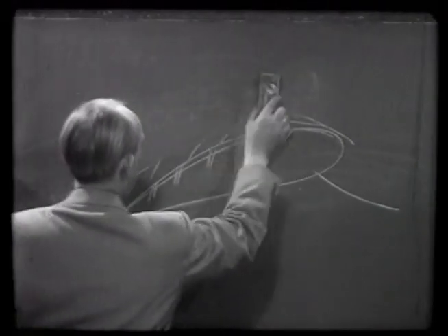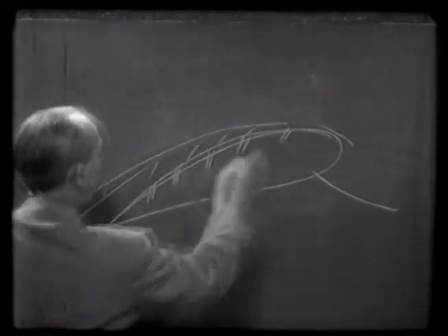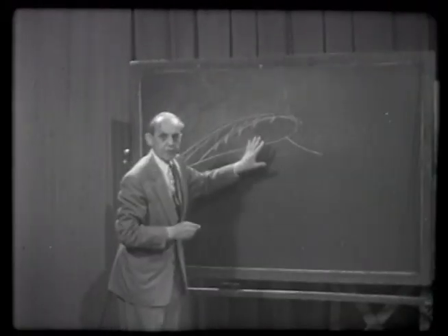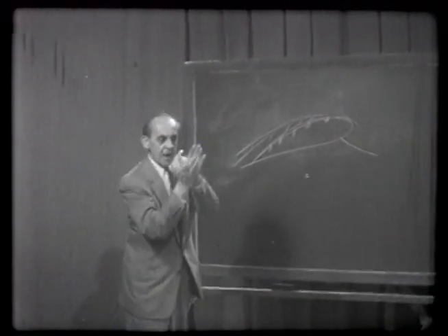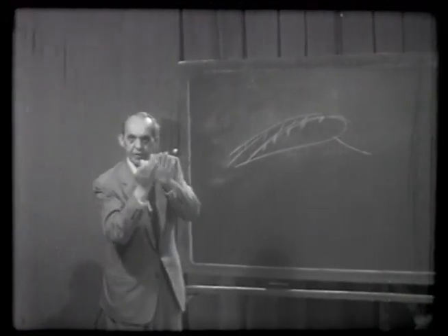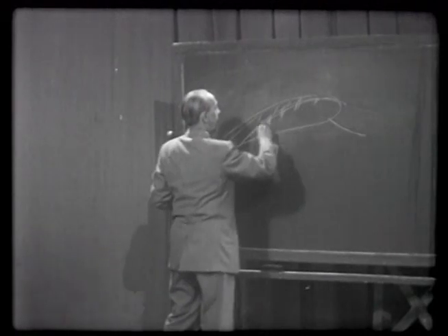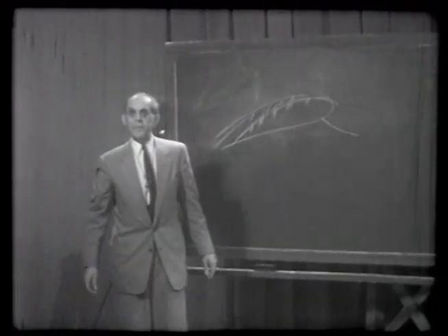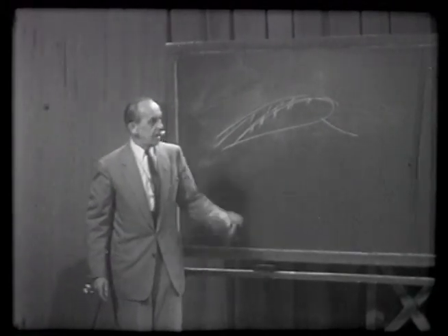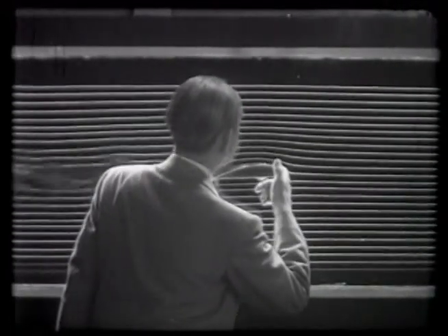This air zone, which is here between the wing and the surface, as you know, we call the boundary layer. The layer which is in the boundary between the wing itself and the outer air. We suck part of this boundary layer away, and in this way achieve a very high lift. I have here a model in this tunnel which has little slots on its surface, actually several ones.